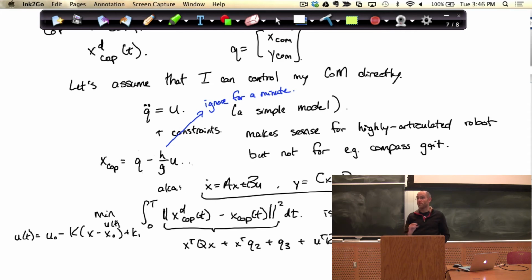So okay, there's a question about how can I write down my constraints on the acceleration of u given the constraints on the whole body? That's a harder problem. But even at this level, there are some constraints that we've ignored, and we could put those in. There's one level of complexity up, which is putting in the acceleration constraints that we talked about already, you know, can't go outside my support polygon or the like. That you can solve easily with linear MPC.